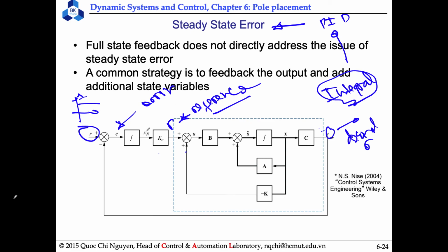And for the PID, because we have the integral, what is the role of the integral here? If we have errors, even if very small, the integral will accumulate them with time.